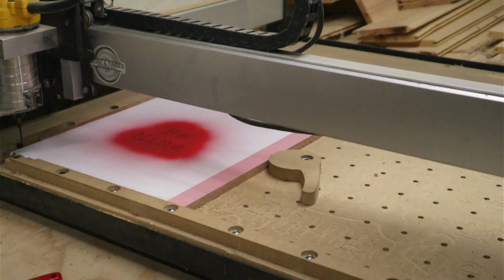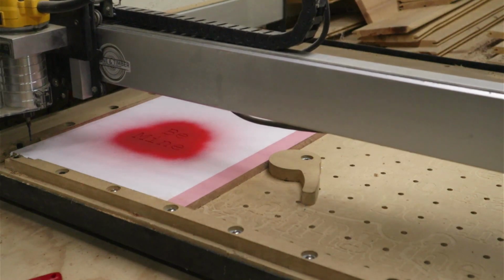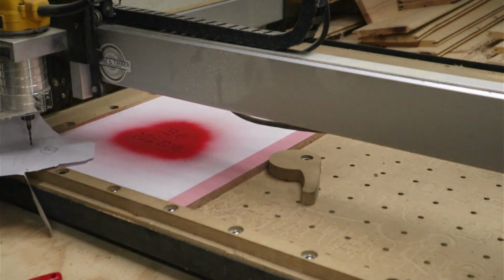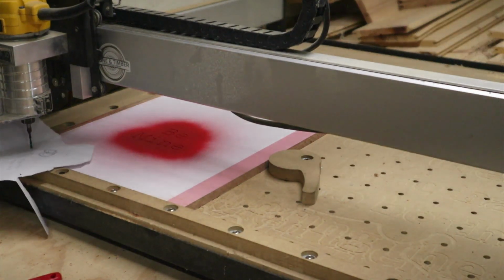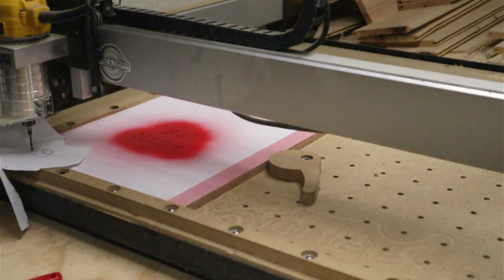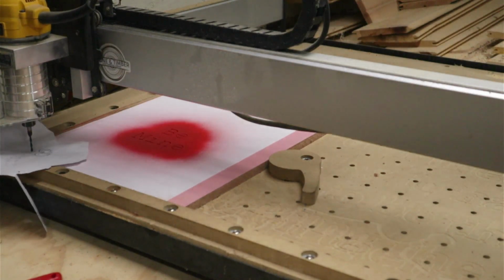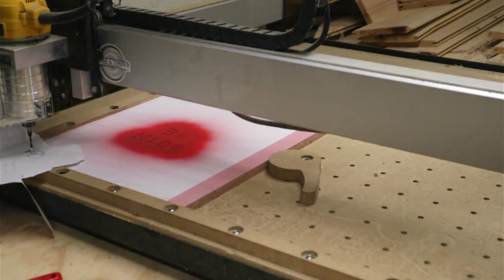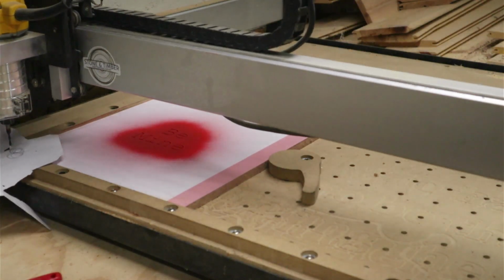Just like before, I set the Z-axis to 0, and the way I did that is I moved it out on the workpiece a little bit and used that paper, put it underneath, brought the bit down until the paper didn't move, and then I set it at that point. Now, one thing I wanted to make sure of is I definitely got it right on the top of that surface, because I need it to cut the whole way through.